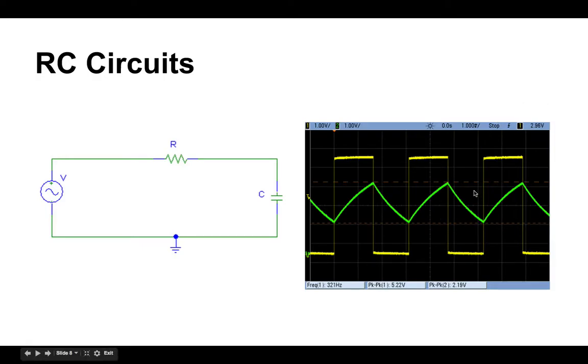So this yellow is what's coming out of pin 2. We're going to look later at inverters that don't have hysteresis, and you would get a triangle wave on the output instead of a square wave. You'd get the inverse of the green pulse. So this is the capacitor at its lowest voltage, charges up to the highest voltage, and then as it starts to discharge, we flip down to low. And then as it discharges, this stays low until it flips back to high. And this is happening so fast that it's perceived as audio, right?